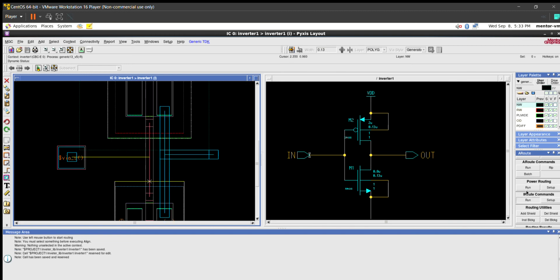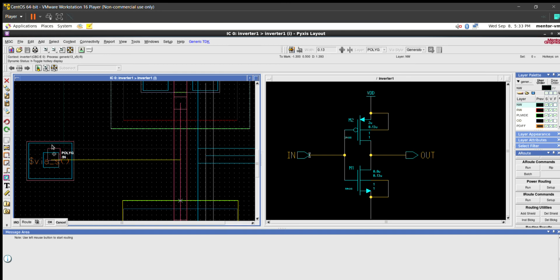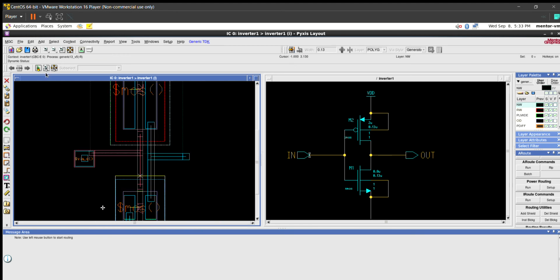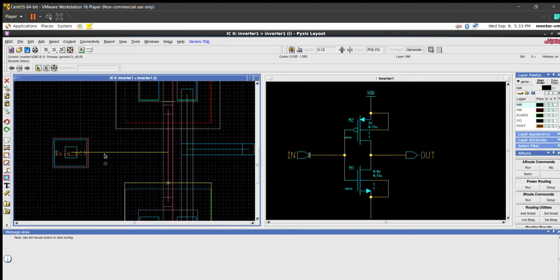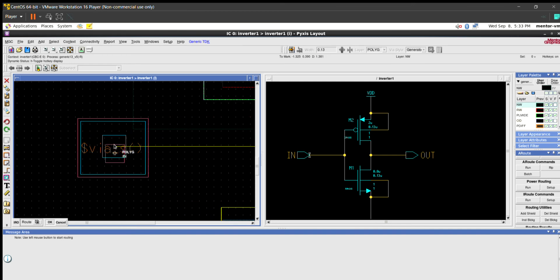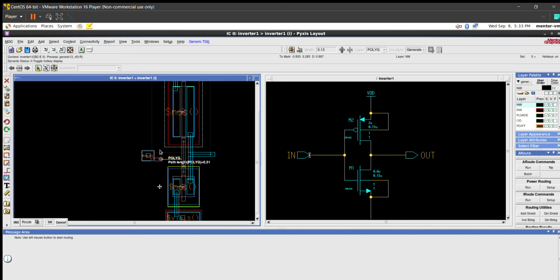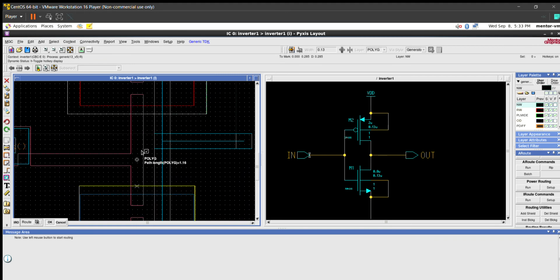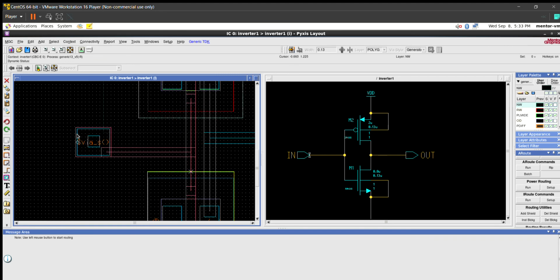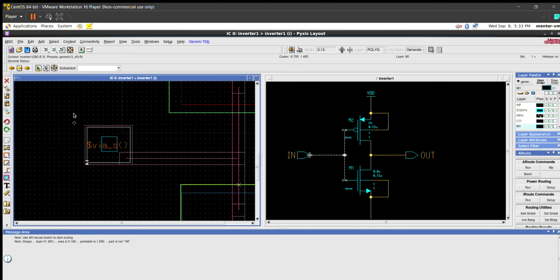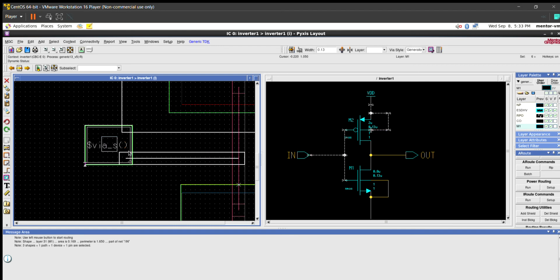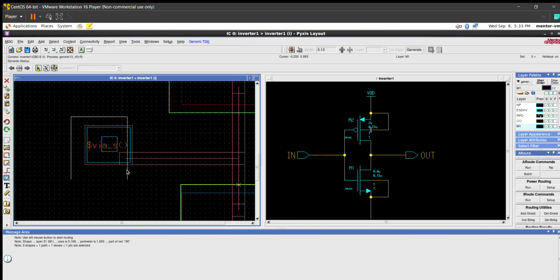We're going to go back to the routing, run, and we want to connect this via to this right here. And this looks good. Let's see, I kind of want to have it more towards the middle. Let's see if that's possible or if it automatically, so it looks like it automatically chooses which side, so I could just take this whole thing and shift it myself. Oops.